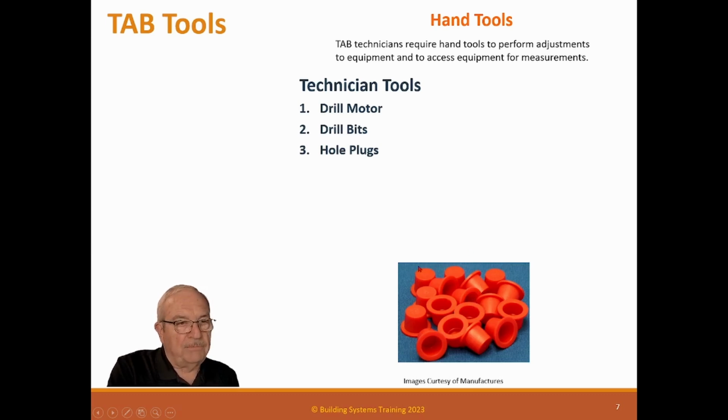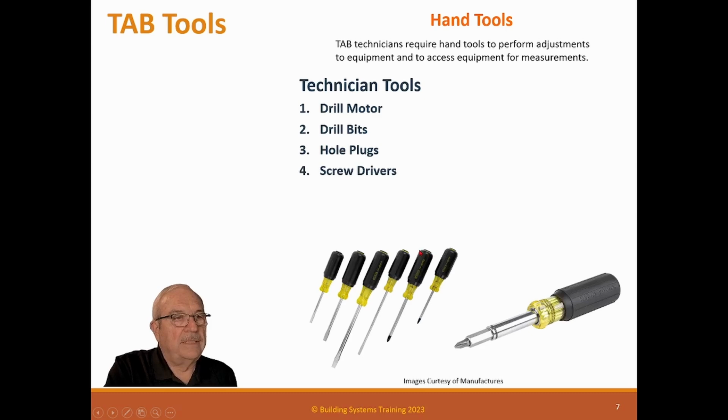Now, I do need to caution you that the plastic plugs are good most everywhere, unless you're drilling into a stainless steel duct or a fiberglass duct that may have acid in it or some other chemical that the plastic won't do. So it may need to be stainless steel. And you'll have to coordinate that with your customer to see exactly what you need. These are cheap. You can buy 1,000 of them for $10 or something.